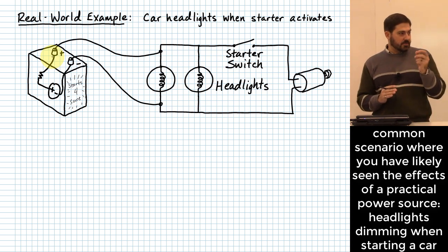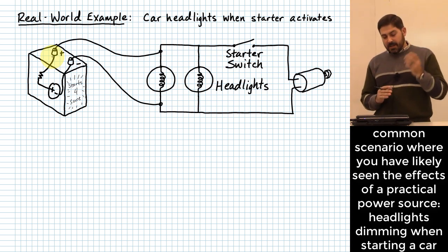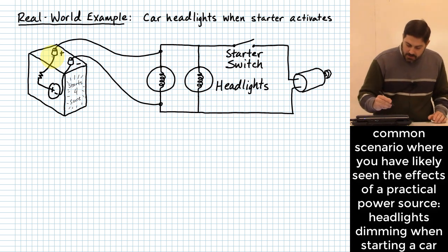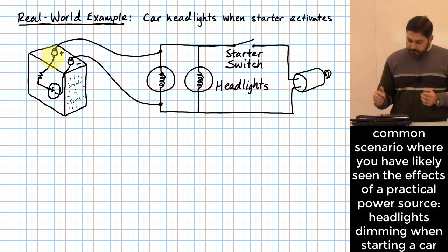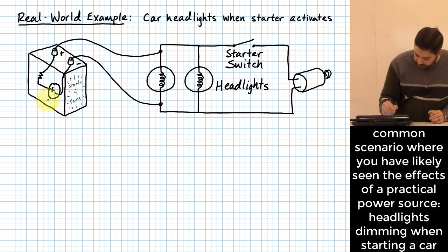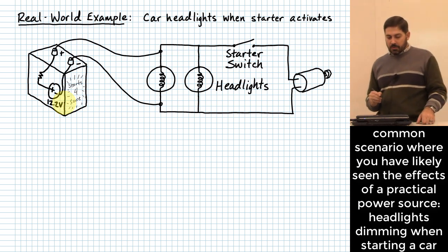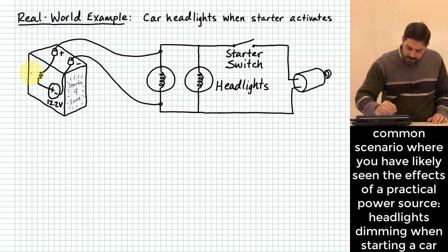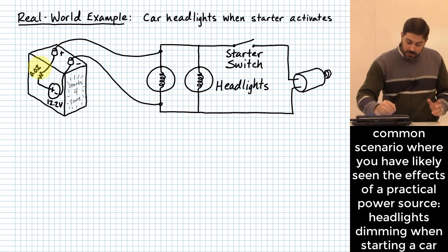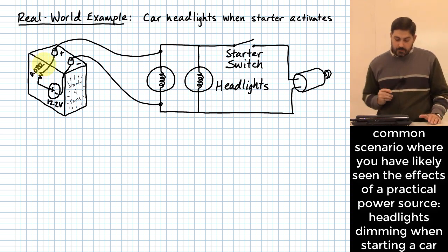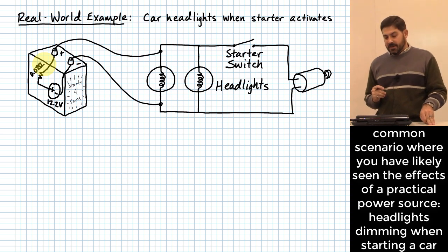So it's not like there's really a resistance in there, but it behaves as if there's one. And so the values that you can typically expect for a battery like this is usually something around the lines of 12.2 volts for the voltage of the ideal source that's inside of that battery, and then maybe something along the lines of about 2 hundredths of an ohm for the resistance that's inside of there.